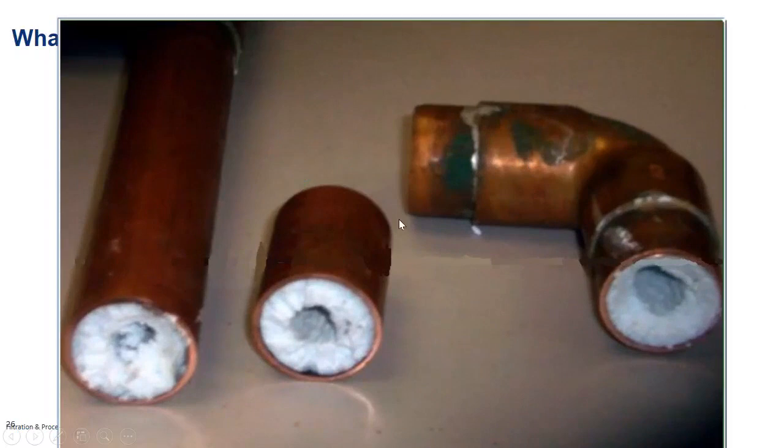And this is just from the temperature change from 52 degrees coming out of the ground to warming up to a 70, 75 degree temperature inside the store in 5 years. This is extreme, but this can happen. This cannot be removed efficiently from the plumbing and open this back up. This store had to be replumbed. That's a huge economic impact. Then there is the economic impact on heating and energy loss.